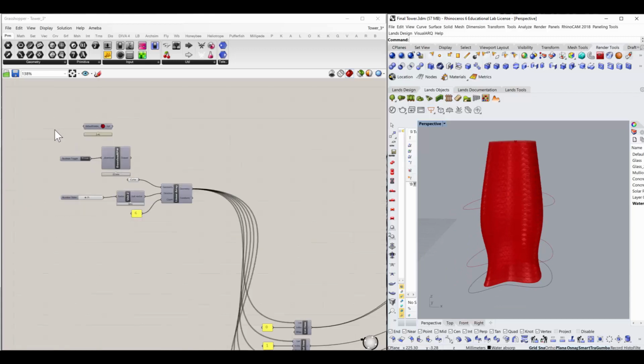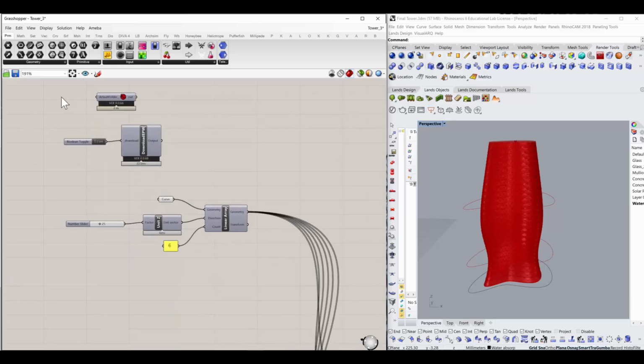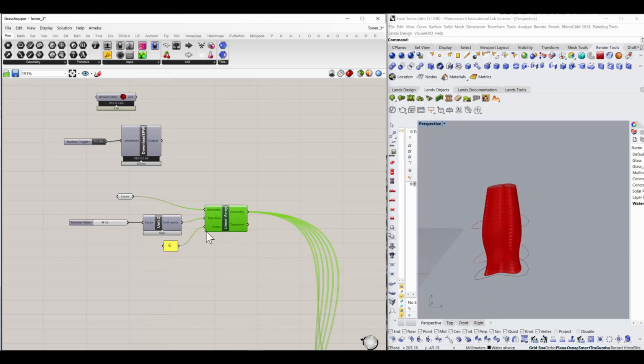First of all, this is the typical thing we do to import an EPW file for Ladybug. This is something we require for Ladybug. Here in the first step we took this curve, which is the bottom green highlighted curve, and we made a linear array of this curve. What this means is this curve can be multiplied in the vertical z direction.